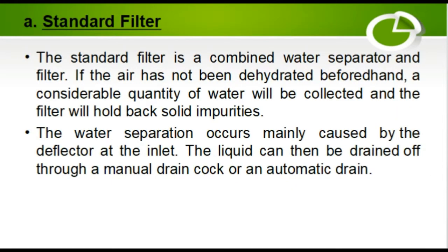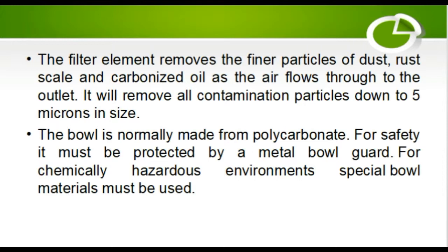Standard filter. The standard filter is a combined water separator and filter. If the air has not been dehydrated beforehand, a considerable quantity of water will be collected, and the water will hold back solid impurities. The water separation occurs mainly because of the deflector at the inlet. The liquid can then be drained off through a manual drain cock or an automatic drain. The filter element removes the finer particles of dust, rust and carbonized oil as the air flows to the outlet. It will remove all contamination particles down to 5 microns in size.